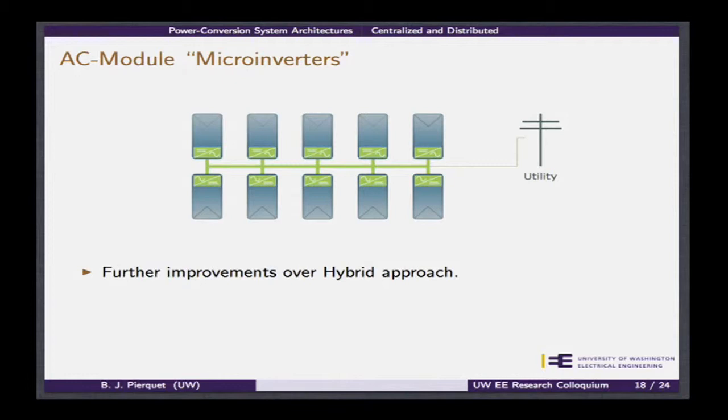A lot of times these are targeted at residential, and so they'll do the US split phase 240, 220 volt phases. And occasionally now they're moving into the 208 three-phase, and there's been some rumblings about trying to go to a 480 three-phase as well. Higher the voltages, you have a larger voltage transformation ratio you need, the more difficult it becomes. And at higher voltages, the protection of these circuits is even more important. The performance of the high voltage semiconductors aren't as good as the low ones, and so there become some trade-offs there. And so with designing each one of these power converters independently, we have the trade-offs of simply having to make a bunch of them.